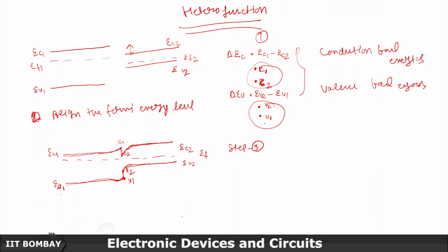So if I summarize what we did today, the take home message is that metal semiconductor junction can be rectifying, can be ohmic, okay. So they can be both rectifying or ohmic, depends on the relation between φm, φs. Also depends on the doping level. Like doping level is very, very important.